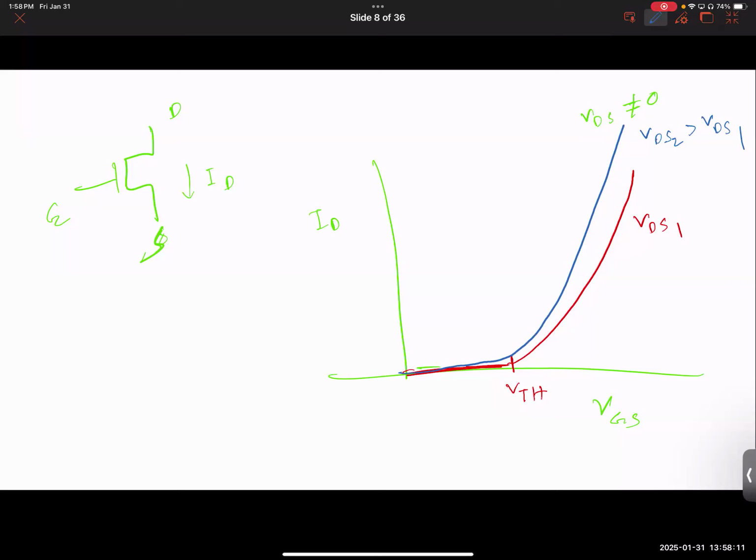And then we discussed, well, for several decades, we kind of ignored whatever happens below threshold voltage. But now that we are dealing with billions and trillions of devices and components, we can no longer ignore it. And then I gave you an example of how a billion means 10 raised to 9, and a nanoampere, which is typically the current range here below the threshold voltage, which is by all means negligible. But then when you multiply a nanoampere current with a billion devices, you immediately get 1 ampere current, okay? Which is a lot of current, by the way.